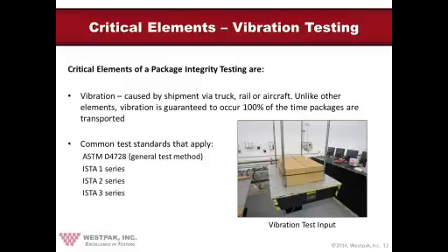As a testing laboratory, we're often asked to compare various types of inputs, primarily in the area of vibration, by the way, because there's a very noticeable difference between something like a rotary bounce test, ASTM D999, and a true random vibration test, which has its origins in data collected from vehicles. So, we're often asked, how can those two be equivalent? And my answer is, they ain't. They just can't be.